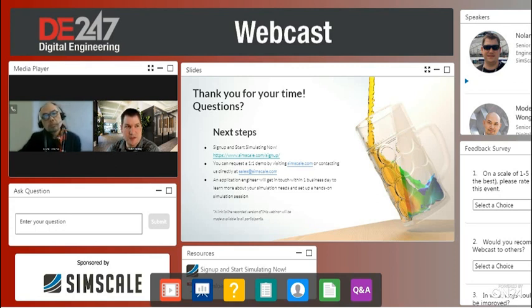So I would say we have an automated approach that is going to be using a combination of tetrahedral cells and things like prism layers to capture the near wall boundary layer effects. It transitions to a hexahedral core away from the walls or away from surfaces. We also have a snapped hex dominant mesher as well, again for CFD studies. And then for the FEA side of things, we have a tetrahedral mesher, and we support mid-side noded elements, so say a TET 10 element, second order accurate with that type of approach as well.